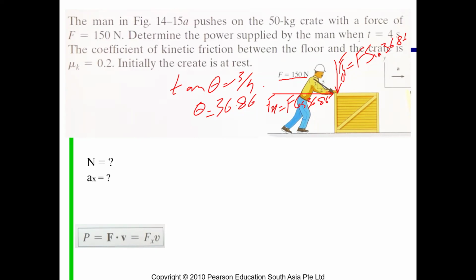If I ask you to draw the free body diagram, this external force I have already resolved with the angle. What else should be there if you construct the free body diagram? What other forces do you see in this problem? Weight, which is acting like this, right? And weight is 50 kg into 9.81. This will be the weight. What else? Friction. So this F for friction. What else?